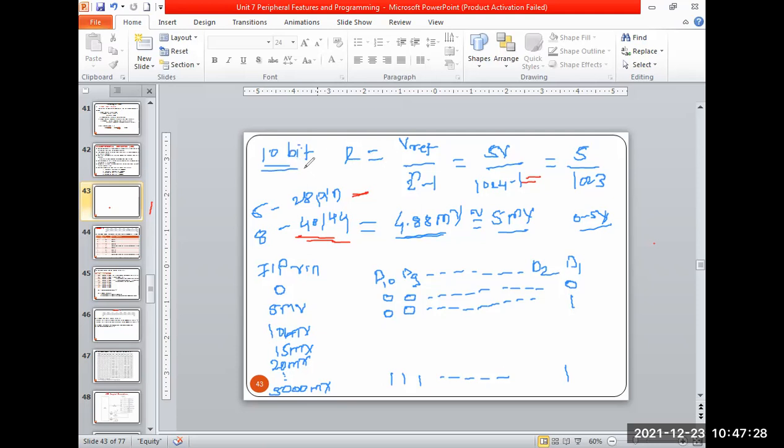That's why as it goes from 10 to 11 bit, the 5 millivolt value will come down to about 3 or 4 millivolt, and correspondingly the number of signal levels available will increase. So this is the basic idea used for analog to digital conversion.